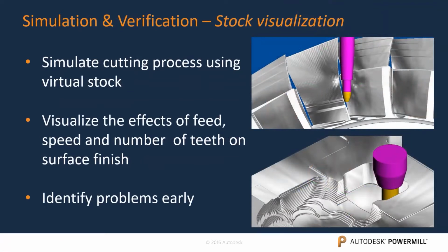Simulation and verification. So we do have a stock simulation. We also have the ability to identify those problems early with that and see the effects of feed speed, number of teeth, and surface finish.